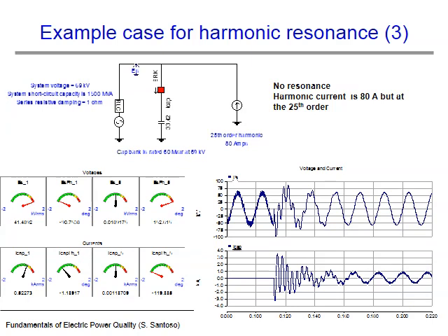The energizing operation is repeated once more, again with 80 amps of harmonic current injected into the system. This time, however, the current oscillates at the 25th harmonic frequency. The transient response to the capacitor bank energizing operation now closely resembles that in the first example, with no harmonic current present. These examples show the importance of identifying any resonant frequencies in a power system and ensuring that harmonic currents at or near these frequencies are not introduced into the system.